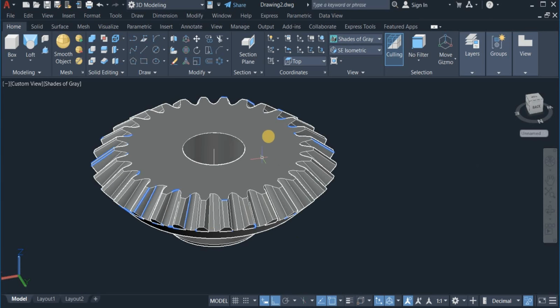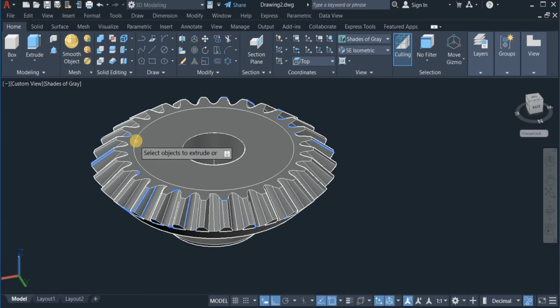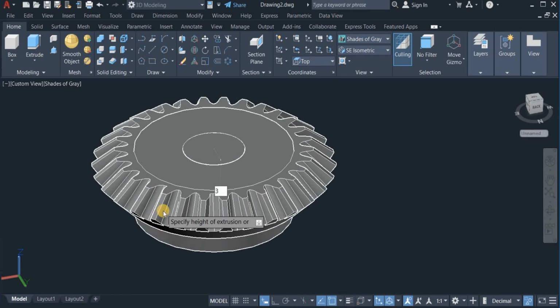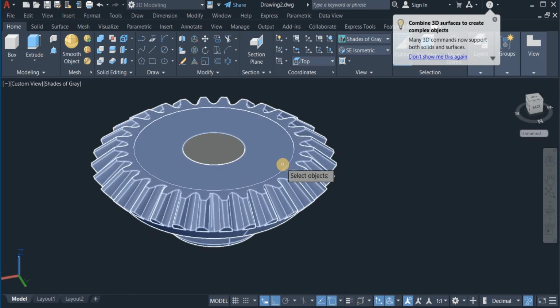Okay. So I also have to apply the recesses here. Draw a circle again, at this point, diameter 64. Now use the extrude command, extrude this circle by 3 down. Extrude down to 3. Now use the solid subtract command. Click on this and remove this.